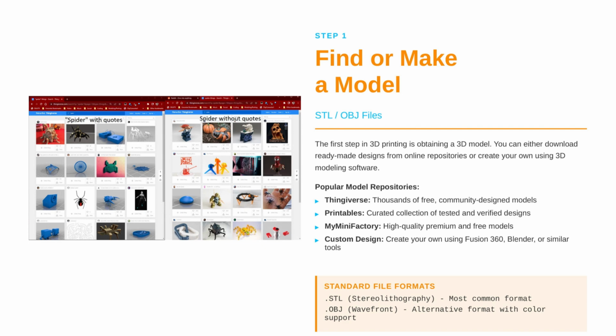Conversely, the OBJ format offers a more comprehensive data structure, capable of storing texture maps and complex surface data. Engineers and designers utilize sophisticated CAD software, such as Fusion 360 or SolidWorks, to generate these models, ensuring adherence to design for additive manufacturing principles. Alternatively, vast repositories like Thingiverse provide pre-validated models, accelerating the design-to-print cycle. Once the model file is secured, the next critical step is preparing it for machine execution.